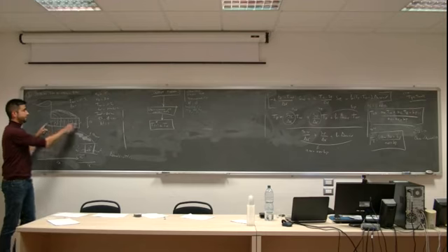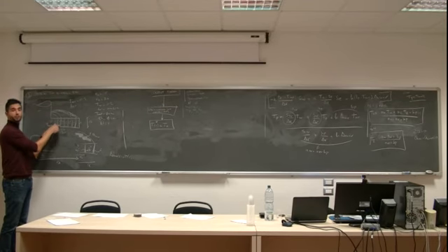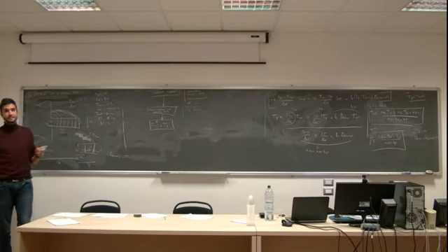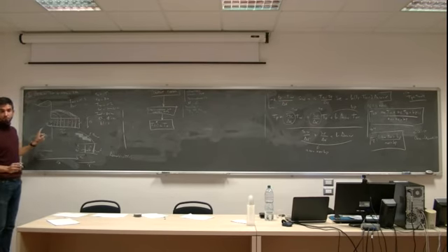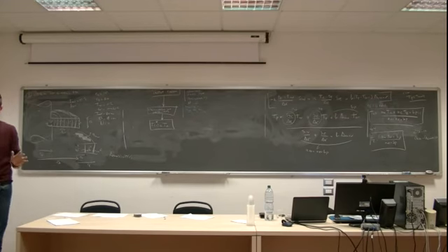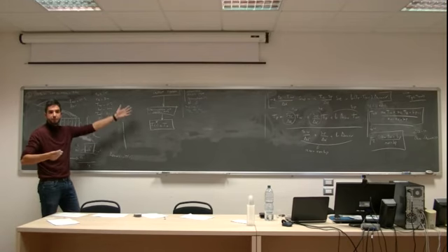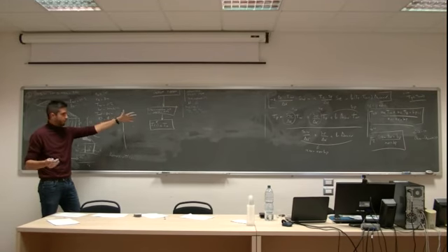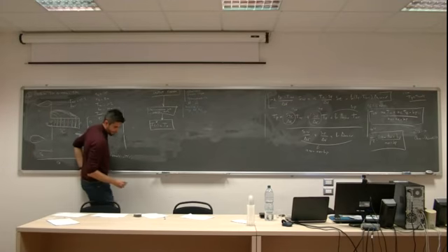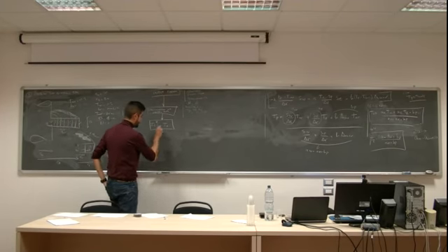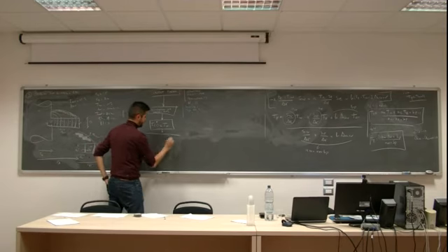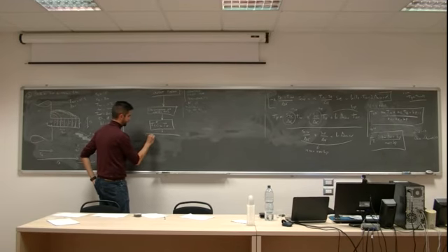So now, I don't know what is the thermal distribution of all these. To calculate T1, I don't know the value of T2. But I will assume, for example, that everything is at 70. I know it's incorrect, but it's somewhere where we can start. It can be 70, 25, 30, whatever value you like. The model will converge anyway to the solution. Now, with this assumption, I will start doing what is called Gauss-Seidel.